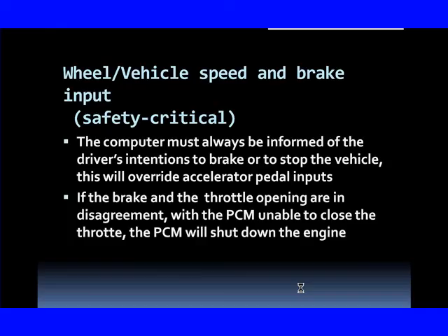We talked early on and gave you those theory things about the system having spark and fuel enable. Well, the reason it has spark and fuel enable is if it thinks it has lost control, it will pull those two enables and shut the system down. Now, this is the last resort. We're going to talk about it more later. But what you need to understand is every time this system thinks something's wrong, it's going to take some action, not as drastically as this necessarily.